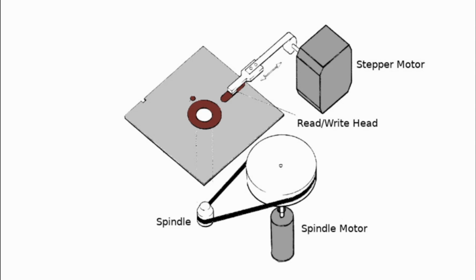the head is on. The Apple II drives have 35 tracks spaced 48 per inch, so the head doesn't move far. The head can be made to write magnetic pulses on the track as the disk spins. These magnetic pulses stay in place until they're overwritten and can also be read through the head.